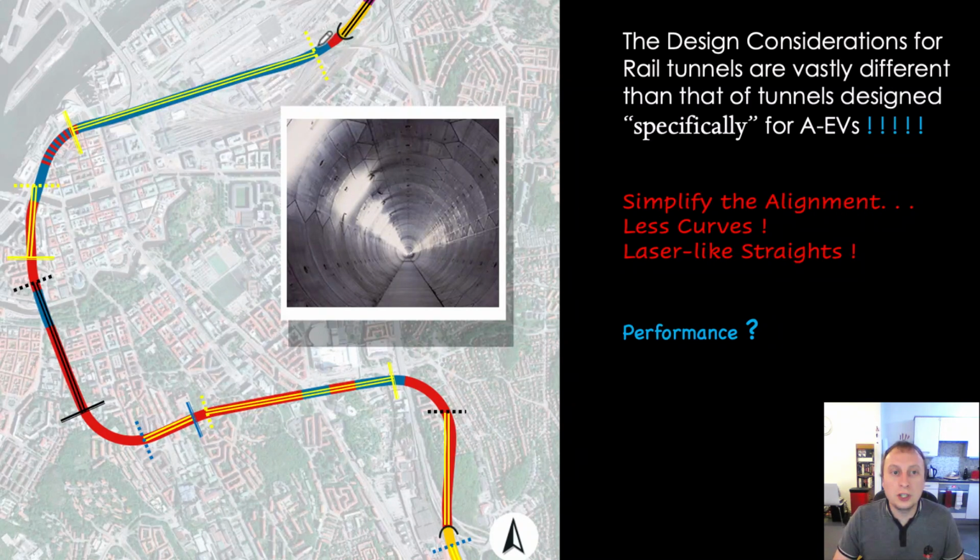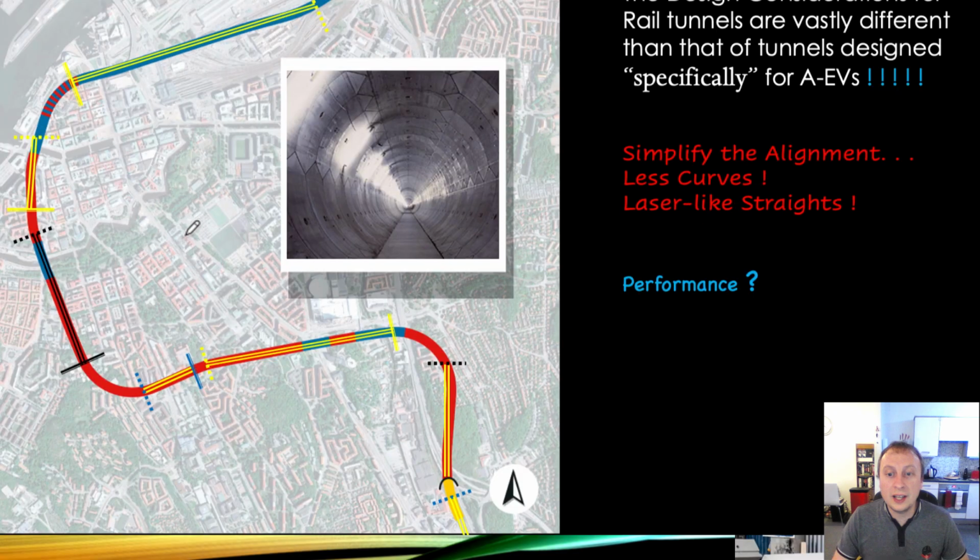So I'm focusing on my straight areas, high performance. When I get to my corners, I'm focusing on keeping the length of that curved alignment as short as possible. And you can do that in the design phase before you've even gone on site or dug your first tunnel. So that is the approach.